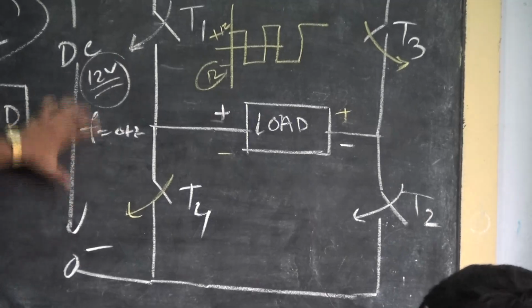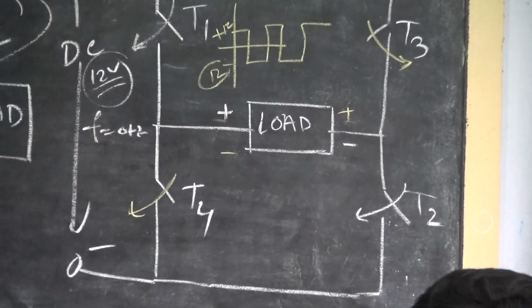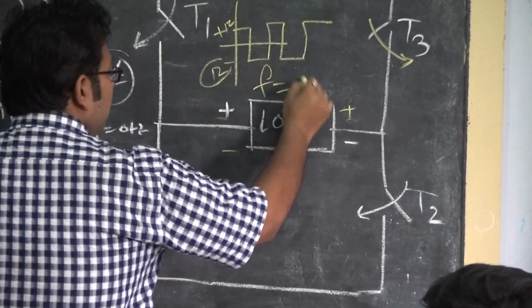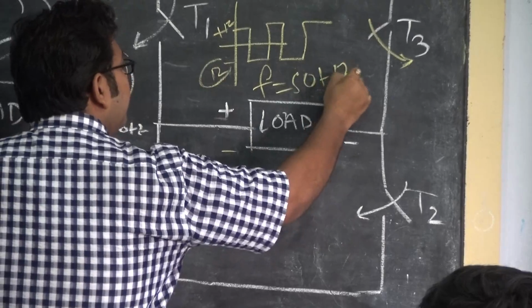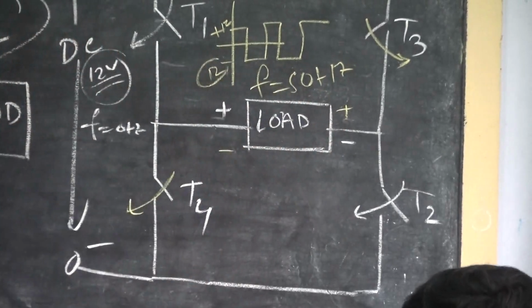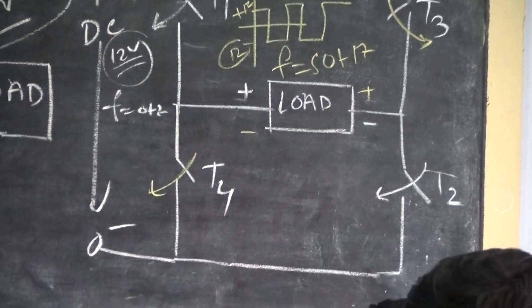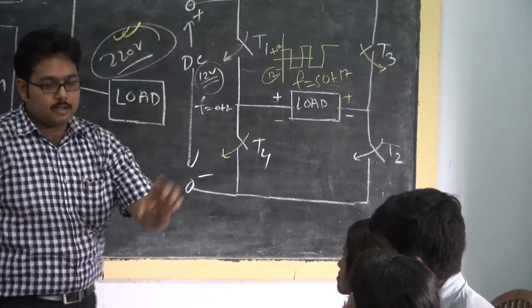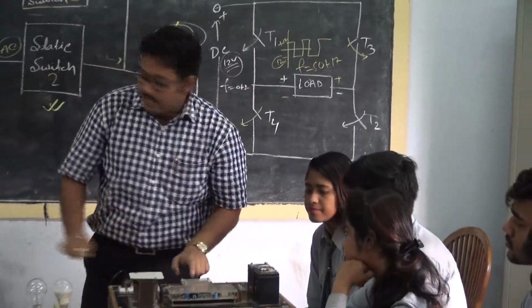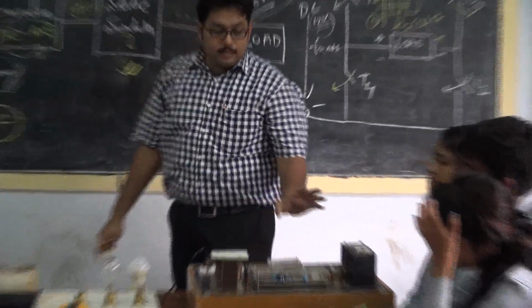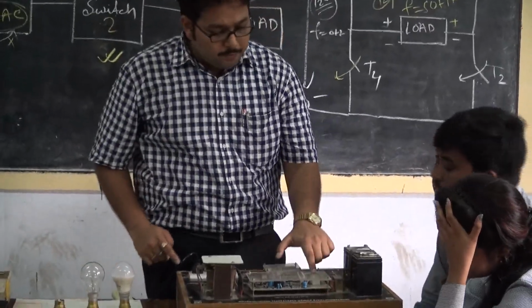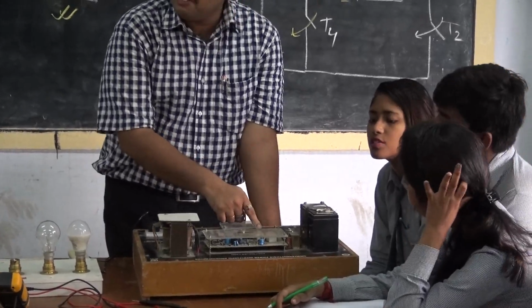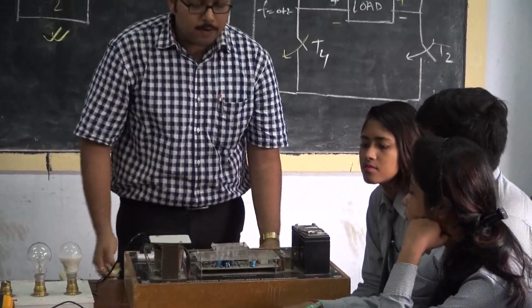Okay, so here the frequency of the DC signal is 0, but across the load now the frequency is present, about 50 Hz. It will depend on the switching time period. So for inverting purpose, this circuit is here. Next, static switch. Actually, in this circuit, a static switch is not present. Instead of a static switch, here we are using the relay in anti-parallel operation.